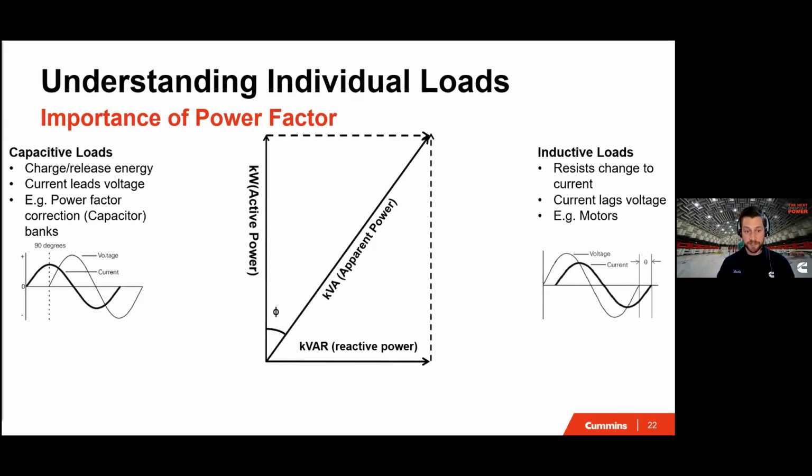We need to be vigilant to ensure the power system being designed remains in the sweet spot when it comes to power factor. And that is generally between 0.8 lagging, on the right side of this image here, and unity, 1.0 power factor. There, we are making the most efficient use of fuel, that is, to produce wattage to actually drive a shaft of a motor, for example, rather than using it to create magnetic fields.